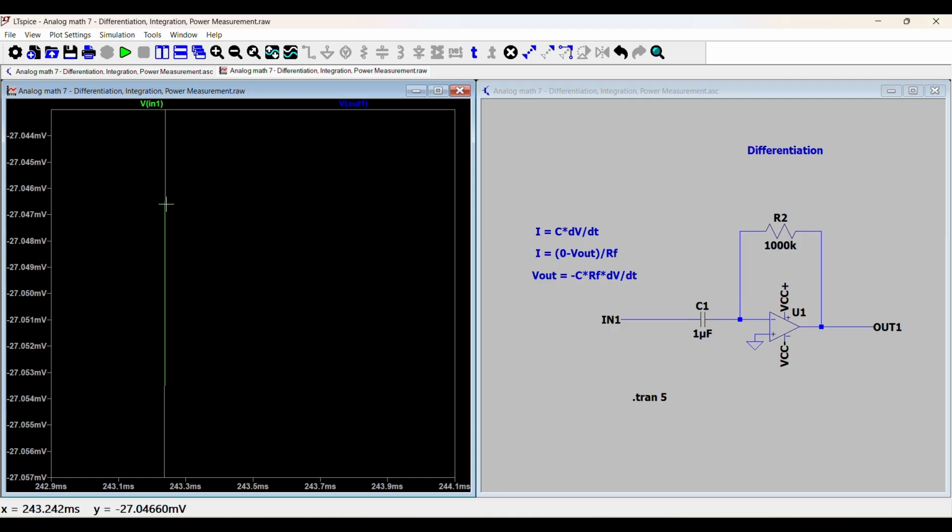And when the simulation runs, because the change in time is 0, what happens is dV over dt is basically whatever this little difference is in voltage divided by 0. So it actually gives an infinite current whenever the voltage changes in the input. So that's why you get these sort of unstable states.